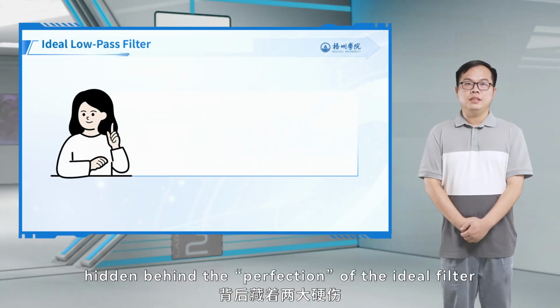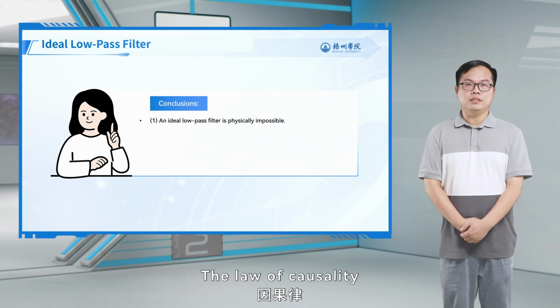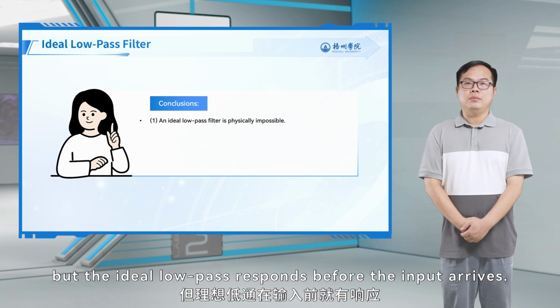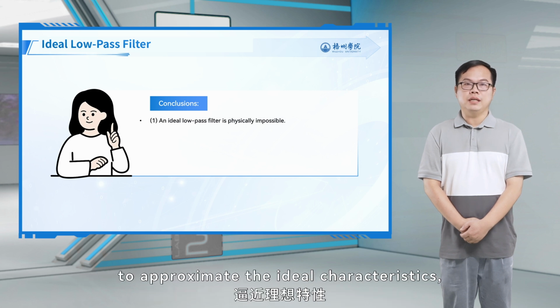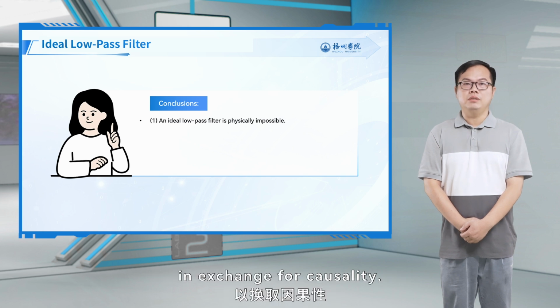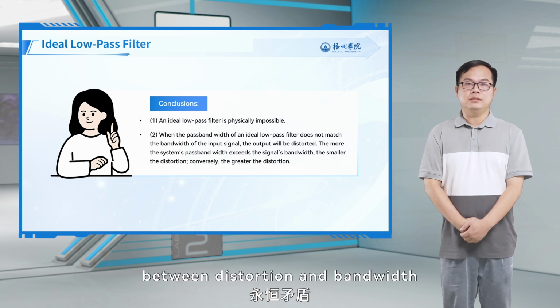2 major flaws hidden behind the perfection of the ideal filter. Flaw 1. Physical impossibility. The law of causality requires that the output cannot occur before the input, but the ideal low-pass responds before the input arrives. Solution. In practical engineering, use realizable filters, such as the Butterworth filter, to approximate the ideal characteristics, accepting small passband ripple in exchange for causality. Flaw 2. The eternal contradiction between distortion and bandwidth.